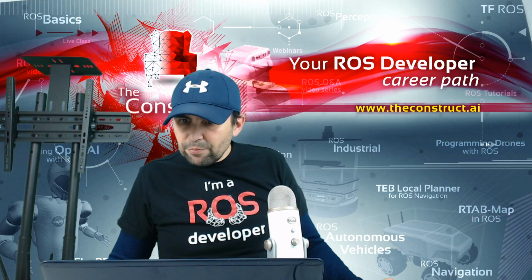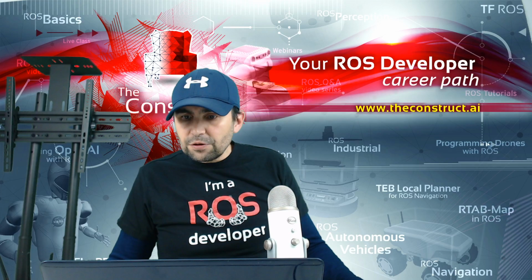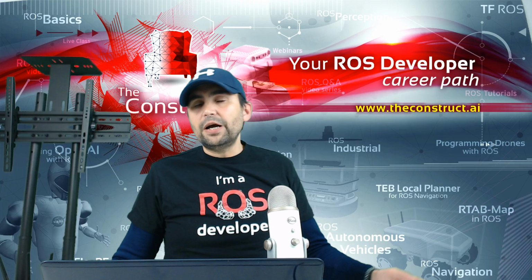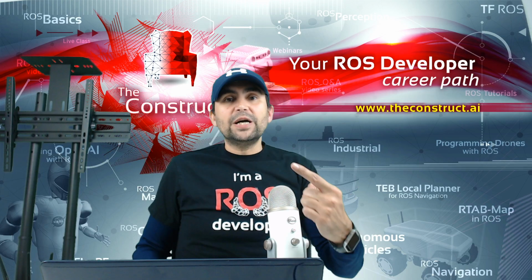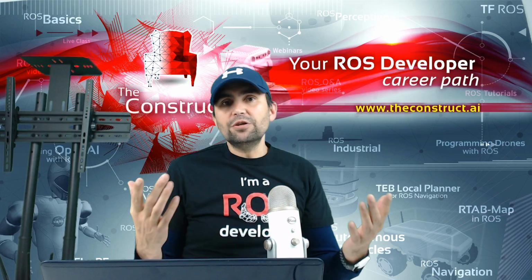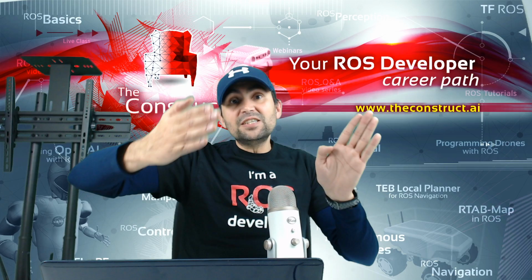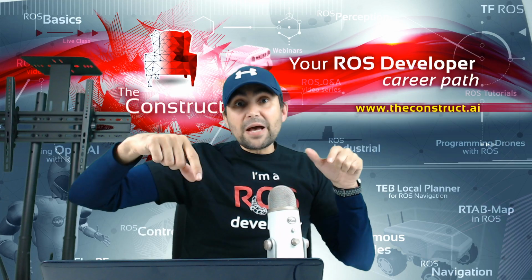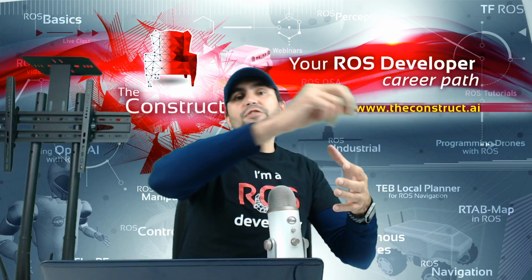Emre says, when we use Cartographer, we can use landmarks, but I couldn't find any information. Okay, so Emre, I'm sorry, I understand what you mean. There are several ways of doing navigation in a robot. One way is by doing SLAM with a grid map, which is what we have seen in the class today. We create a map, and then we match the scans of the laser with the obstacles in the map, and then we compute the probability of being here or there based on this map.